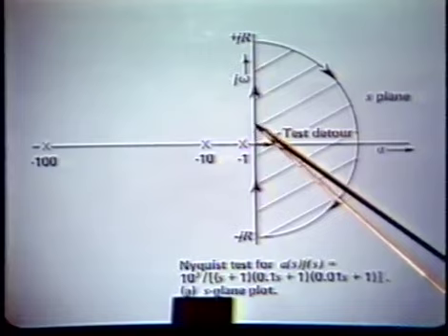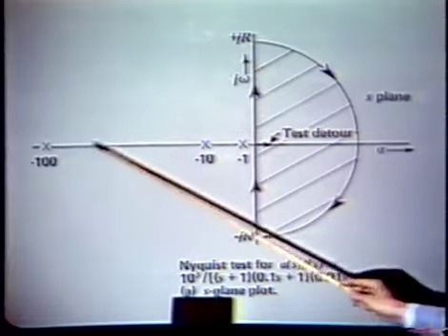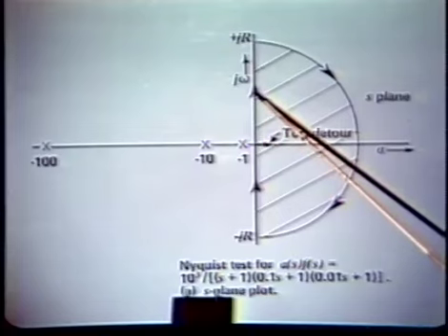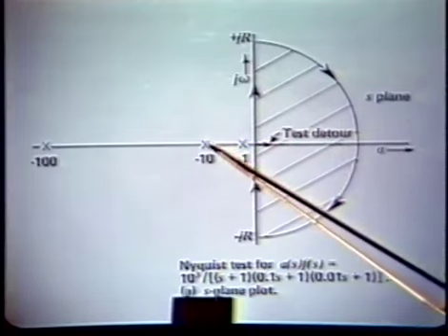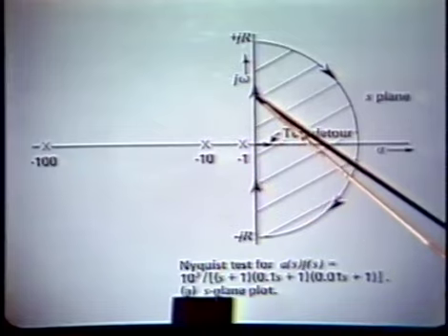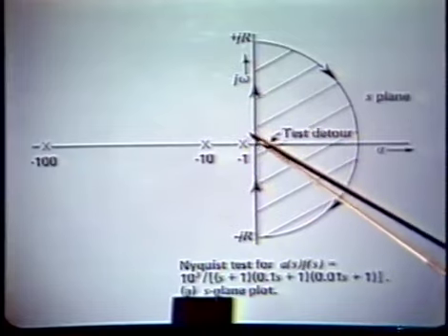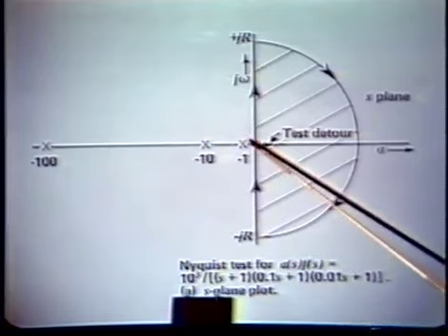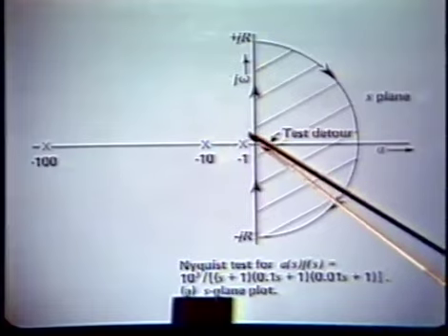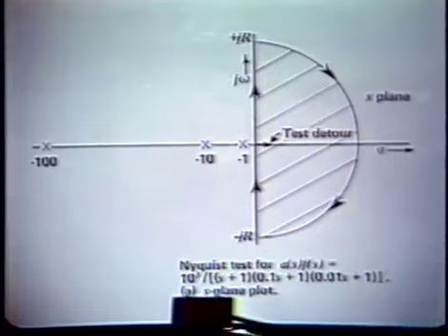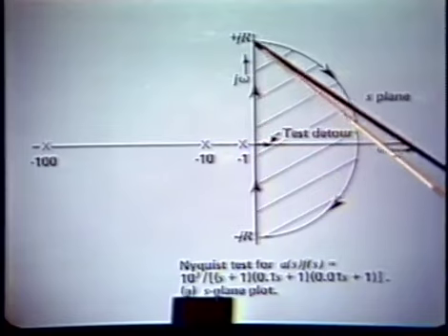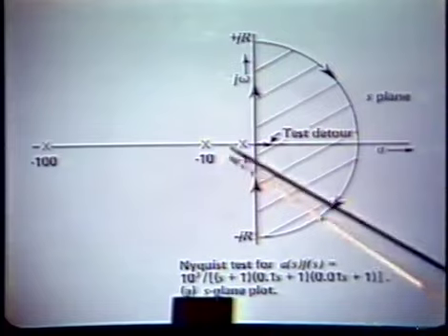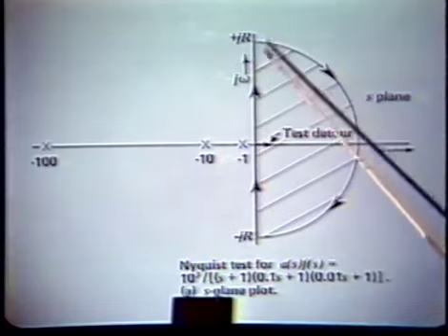And then, since the length of these three vectors to a test point on the imaginary axis increases for increasing values of omega, we'd find that the magnitude of the AF product would decrease. We know its DC value. We know its value for S equals 0. And the magnitude will then decrease as omega increases. Furthermore, as we go to very large values of omega, way out up here in the top of the plane, the angle approaches minus 270 degrees.